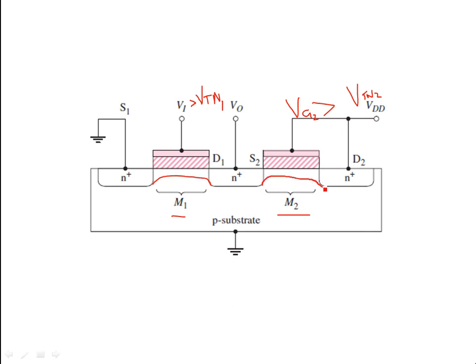Normally the source terminal of an NMOS device is grounded, at the same signal ground as the body. So the body, the bulk or the semiconductor material of this MOSFET device, is at the same ground potential as your source. Now, what happens once you have more than two NMOS devices on a single IC?